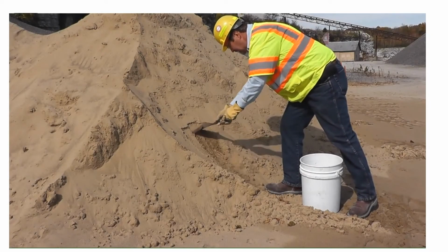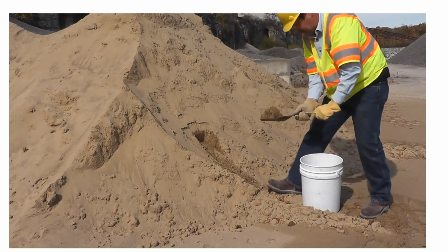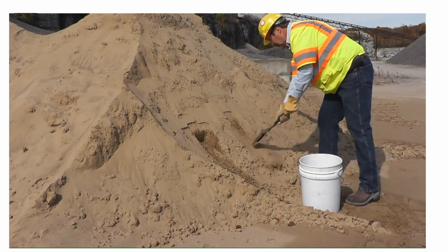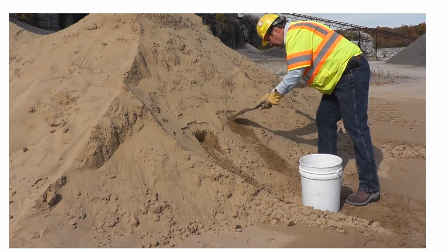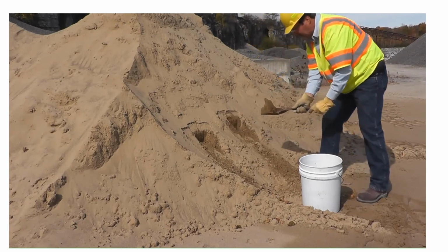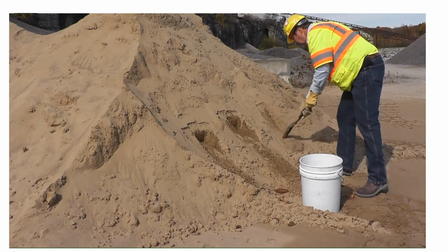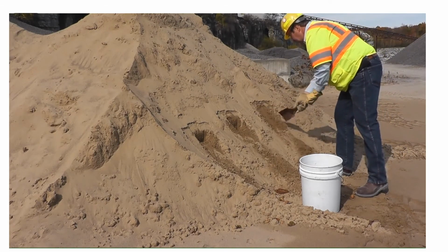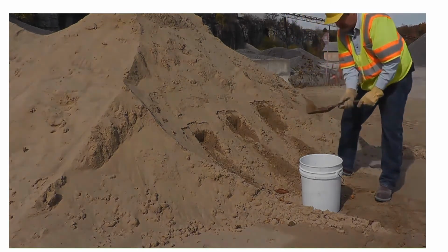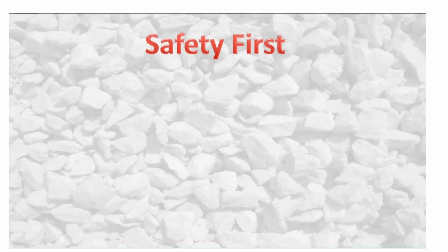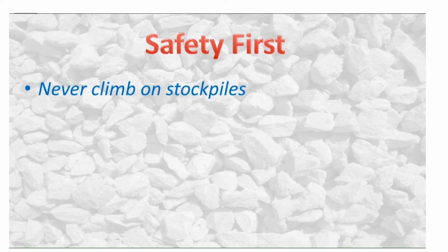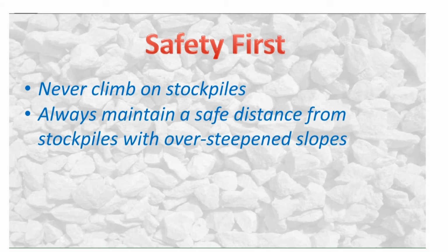In the event that a fine aggregate stockpile does not exceed the height of the technician and there is no apparent segregation, the technician may procure the sample directly from the face of the stockpile. However, before actually obtaining the sample, the technician shall first remove the surface crust from the sampling area or areas. Under no circumstances shall a technician ever obtain a sample by climbing onto the stockpile. Additionally, technicians shall always keep a safe distance from any stockpiles with over-steepened slopes.